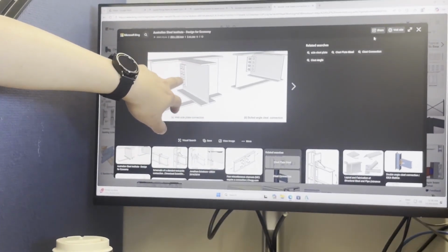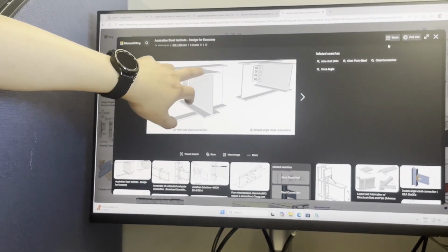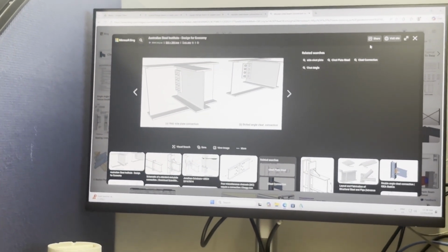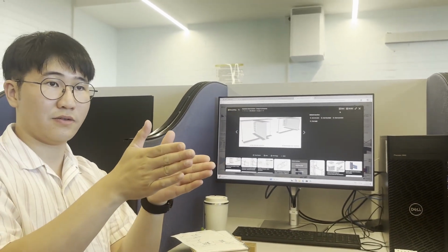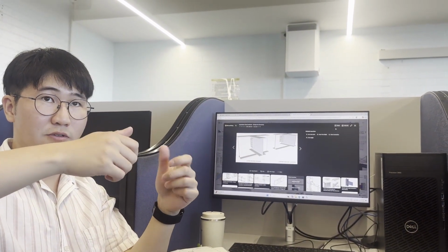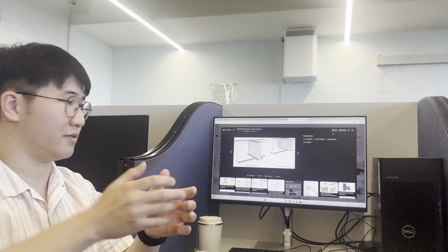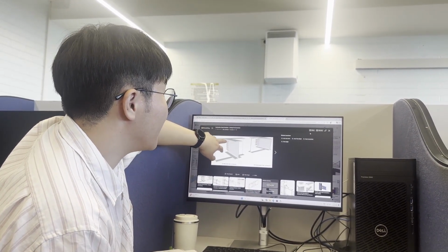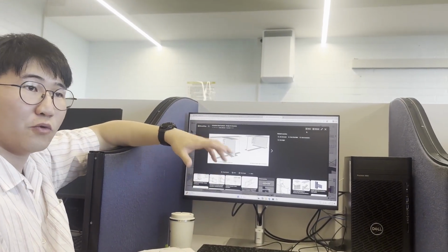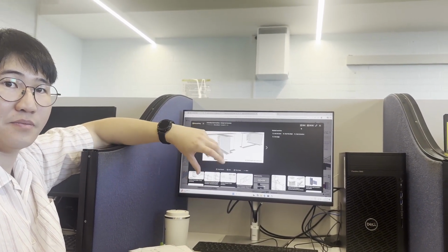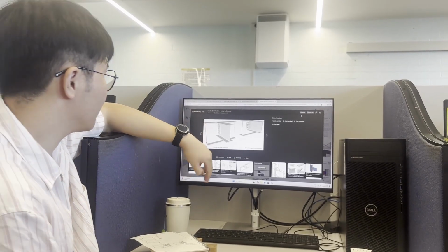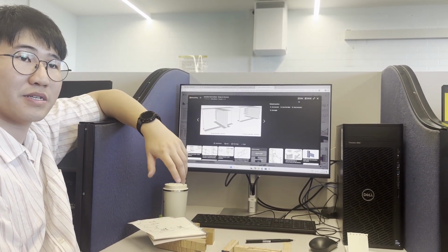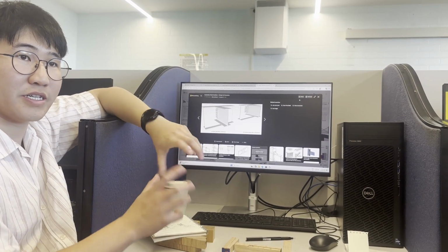okay, it's also a building tolerance thing, right? So if you're welding that in the shop and you weld the other one in the shop, you have to be able to perfectly slide the web of the I-beam in between. And if there's any gap, then you basically have to tension it with the bolts. Anyway, so it's a little bit harder to build. But the reason you generally don't see that is basically the more connection you add, the more rigid it becomes and the less pinned it becomes. So if you only have one cleat on one side, it is more of a pin connection. Okay, you're adding more rotational stiffness basically.